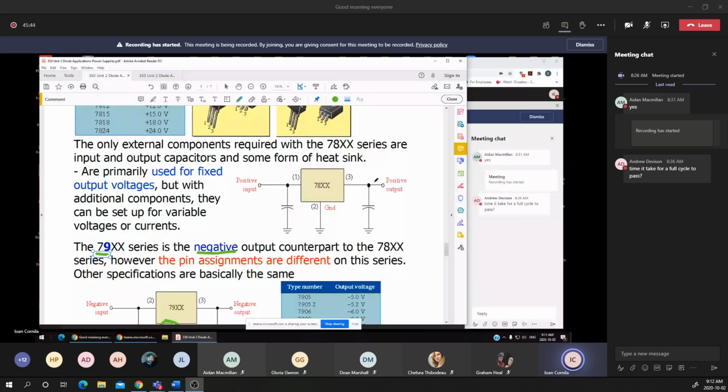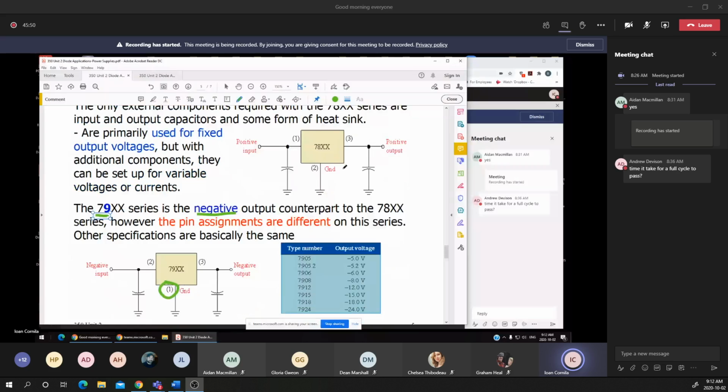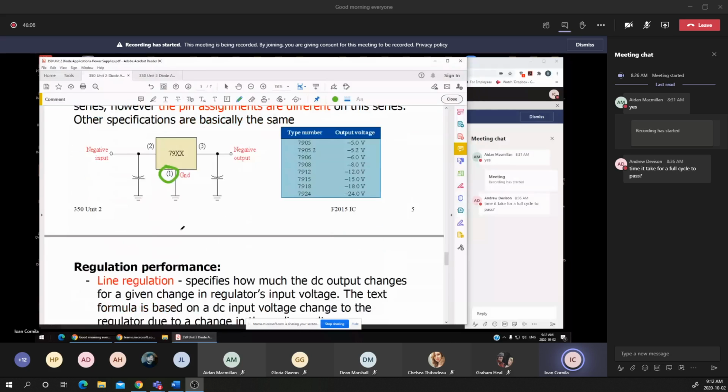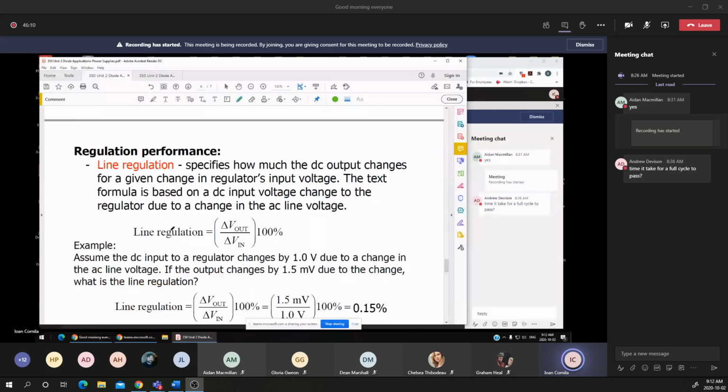They made this convention for 78 and 7900 in order to avoid burning another circuit or another device that is connected to a voltage regulator that was probably replaced with 7900 instead of 7800, and vice versa.